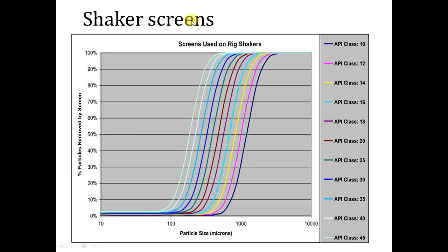Shaker screens are like the sieving at your home. If you see that your mother or your wife is getting the flour and making sieving for the flour, the fine one comes through the sieve, but the coarser one remains over the sieve. This is the same as the screens that we are using for the solids in the mud.